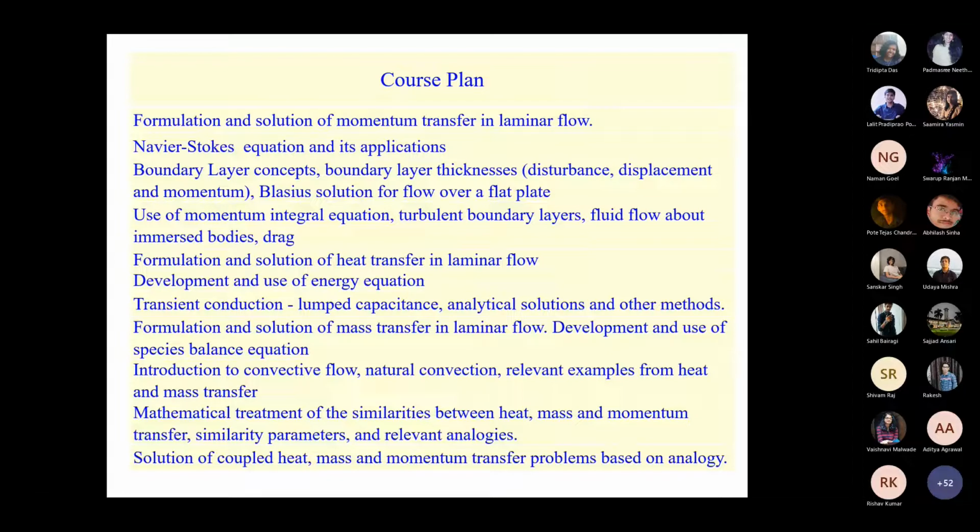It's known as the Biot number, and one should be careful in distinguishing the Biot number from the more common Nusselt number, which is also hL/k. But the difference between these two, can anyone tell me the difference? Am I audible? At least in the Nusselt number, the k which we use is of the fluid. Perfect. In the Nusselt number, the k that we use is that of a fluid.